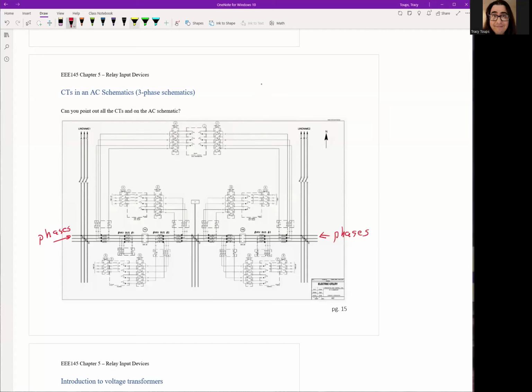Okay. Now, on these wires, you'll notice these 3 things. You see there's 3 coils with the dots, 3 coils with the dots. These are your CTs, right? They'll typically be close to the circuit breaker. So this square right here, this is your CB. This is your circuit breaker. Notice we have 2 CTs on either side of circuit breakers. Why is that? It's because these are slip-on CTs. Remember, on a circuit breaker, you slide the CTs onto bushings. That's what this represents. So it's very common that you'll see 2 CT windings on both sides of every circuit breaker, and we could do our design from there.